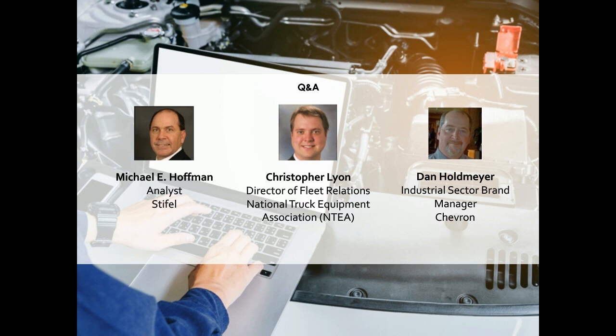Another excellent question. And I'm going to agree with Michael on oil changes, and it becomes very expensive on large trucks. Oil analysis has come a long way, and I believe Dan probably has a whole lot of data to back this up, but starting to build a baseline of your specific oil that you use, you can create a profile of when to change oil. Obviously, most importantly, follow the manufacturer's recommendations, but in some severe duty cycles, we may want to change that to tailor your needs.